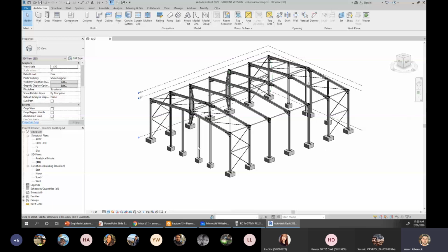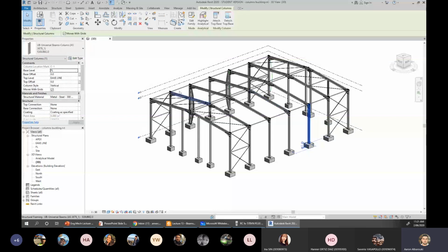These are the main components, I would say, before we start adding purlins and girts, which are other components you will learn later on. They'll be supporting the sheets on the outside. The sheets on the outside are the finished material, and we call them cladding. So that's the main structure of the warehouse, and these main components are resisting all these forces. You can tell this member here is a column supporting the weight of the roof and the weight of all these components at the top.